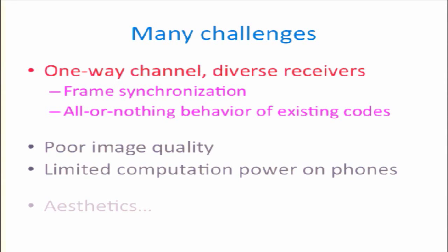And they can be doing this anywhere, right? For example, if I see this screen here, I might be standing here trying to take a picture, and anyone sitting over that corner might be doing that. So essentially, from a communication point of view, this is just a broadcast channel, and with all this diverse hardware capability, you can translate that back into some kind of channel condition as well. So effectively, you have very heterogeneous channels. From a communication point of view, one of the classical issues with a broadcast channel is: what do you do there? Conventionally, you are constrained by the worst user, because you have to make sure everyone gets something.